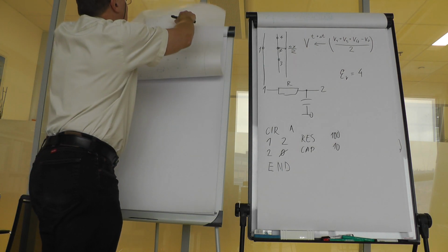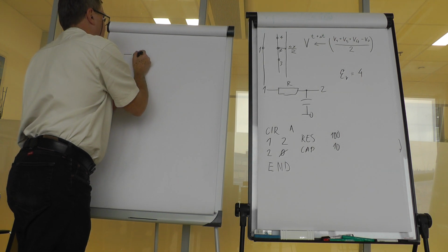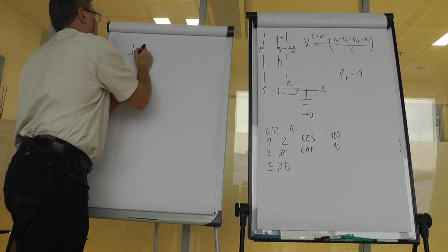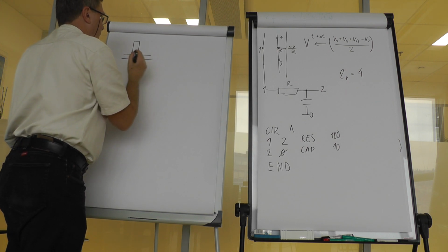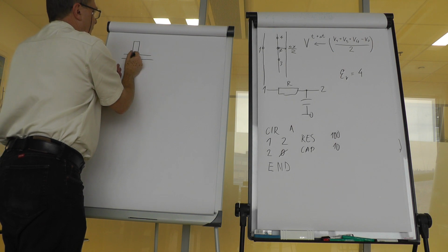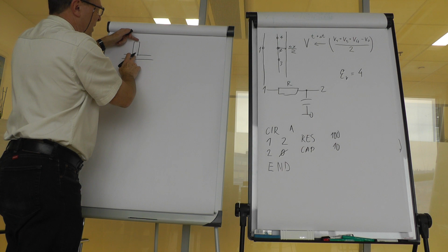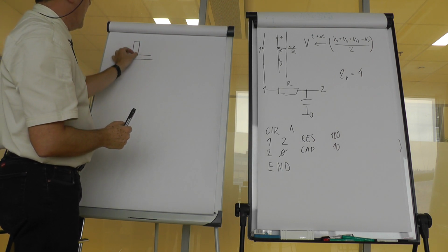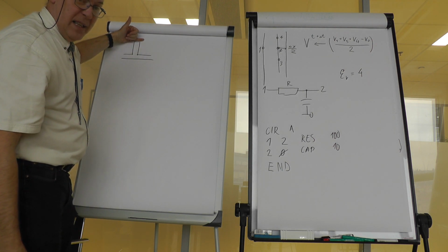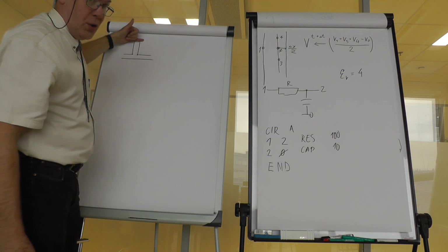But that has been achieved using a stub instead of the line. So you have a transmission line and you cut it and put here another section of the transmission line of a proper length, so that the wave that travels through the line has a longer path. Of course, you have to terminate this somehow. You could terminate the stub by open or short.